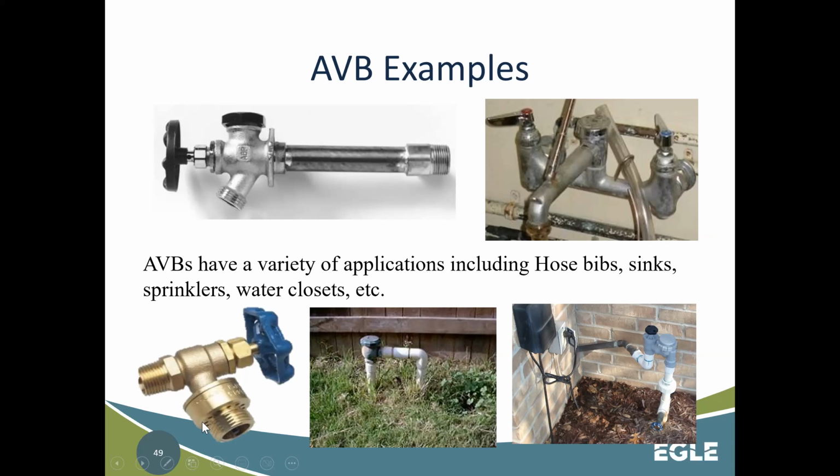This one right here is what's called a hose bib vacuum breaker. So if you're inspecting really old homes, like my parents' house, they don't have vacuum breakers built into theirs. Cities typically hand these out. They're called hose bib vacuum breakers, and a lot of times they'll install them. As you can see, these little holes around the rim, what they do is they don't allow the water to come back through from a garden hose, even if there is a downstream valve, because it creates somewhat of an air gap here and it blows the water out here. Under normal flow, it just flows through. But once this valve's closed, it just kind of sloshes out here around it.